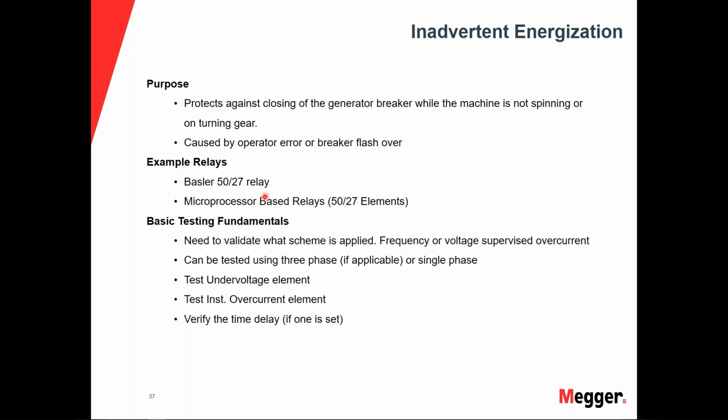Relays, this is the one that Basler has come out with. It's actually a 5027 relay specific for this application. And then also, any microprocessor relay that's putting two elements together in logic, or actually has its own specified relay element for this.